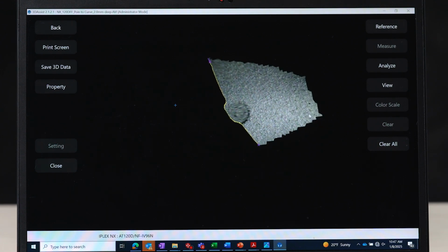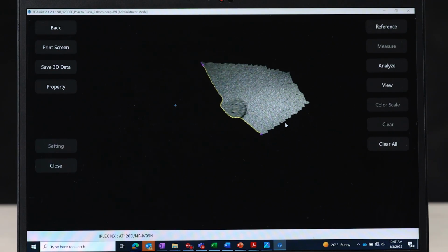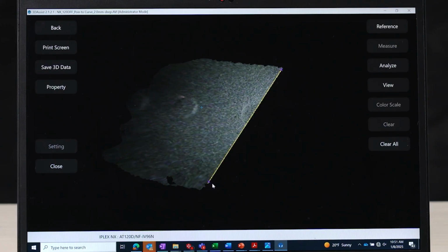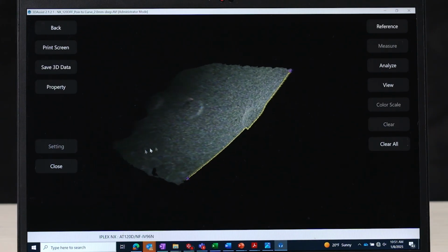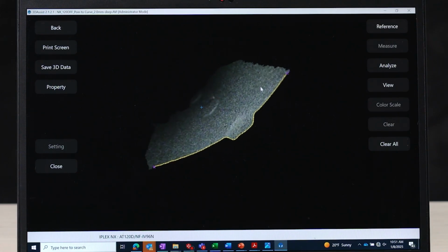Additionally, if a reference plane or reference cylindrical surface is set on the 3D data, the deepest and highest values relative to the reference surface, as well as their positions, will be displayed on the cross-section. In whole view, you can move the points on the cross-section to adjust the range for calculating the deepest and highest values. The yellow dashed line indicates the effective range for the calculation.